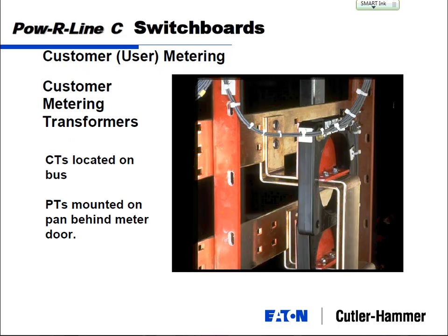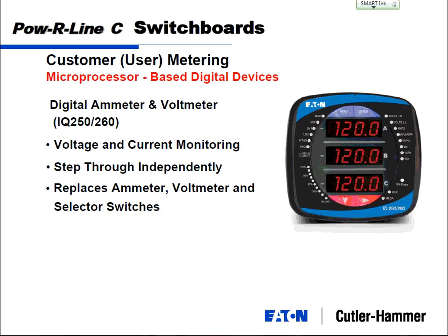In the back of that switchboard, we actually put the CTs around the bus, so this is usually out of view in the switchboard, and so your A, B, and C will come right through these CTs, which feed into the meter. And you've got a few different flavors of meters. I've kind of broken them down into three options from what a customer can expect.